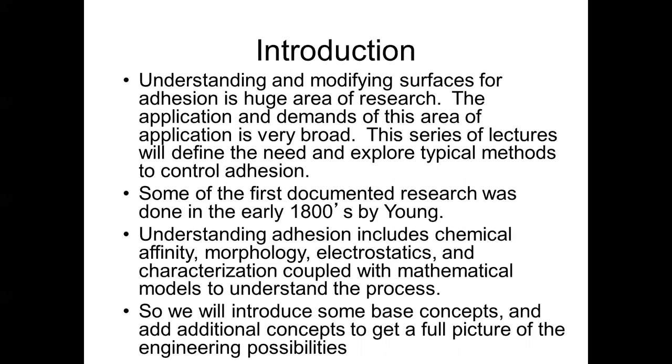So we would like to understand adhesion in as far as chemical affinity, adhesion properties based on morphology, adhesion properties that include electrostatics on a surface, and then certainly we would like to look at characterization methods that are associated with adhesion properties, such as we showed before. We can extrapolate surface energy looking at the angle that a water droplet would make with the surface.